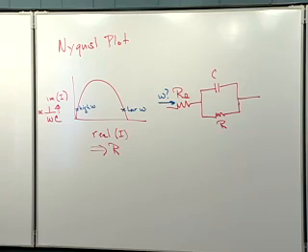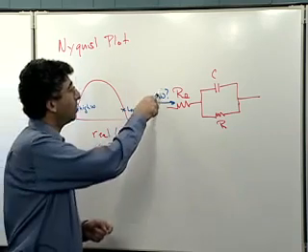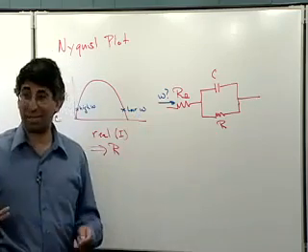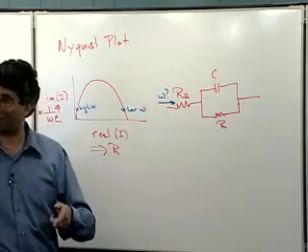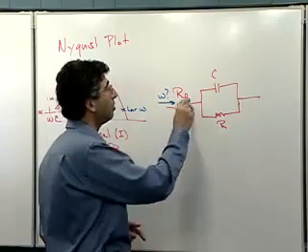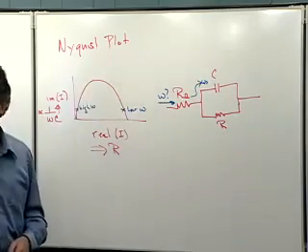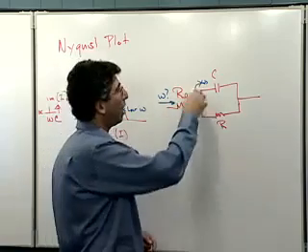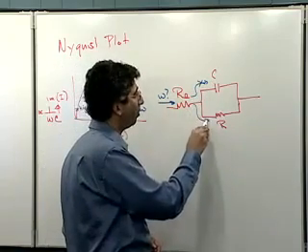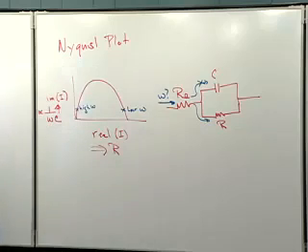Okay. You know that if this frequency is very, very low, let's say it's DC, a frequency of 0, then this path up here is blocked, right? You can't get through a capacitor with a DC current, and therefore this is a high impedance path, and all of the current will flow through the resistor as a result.